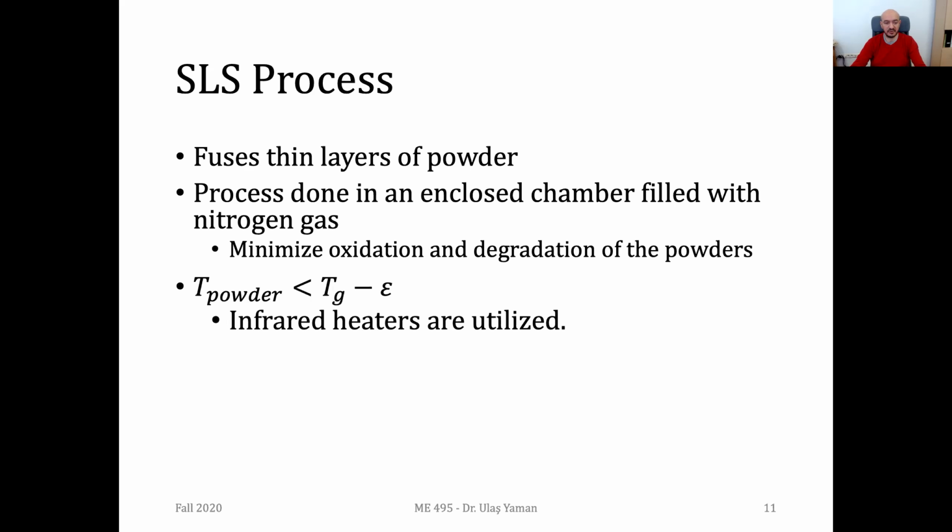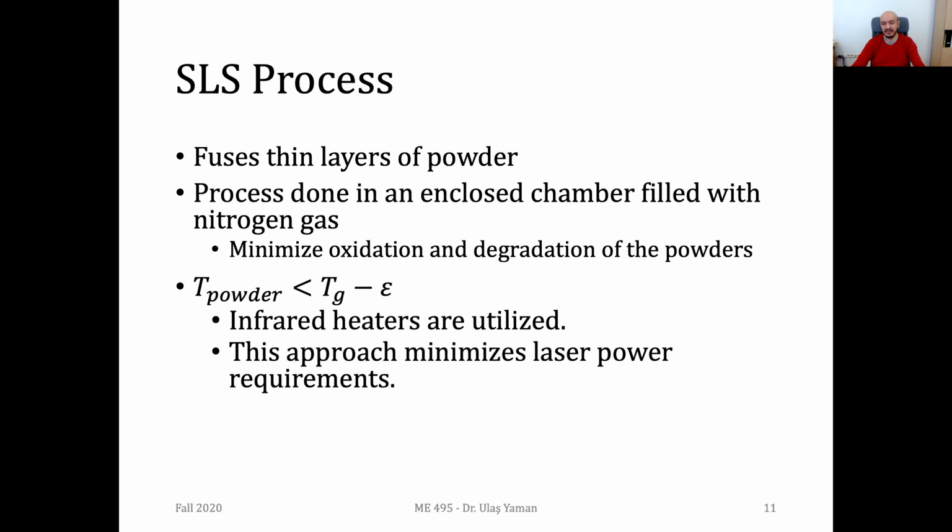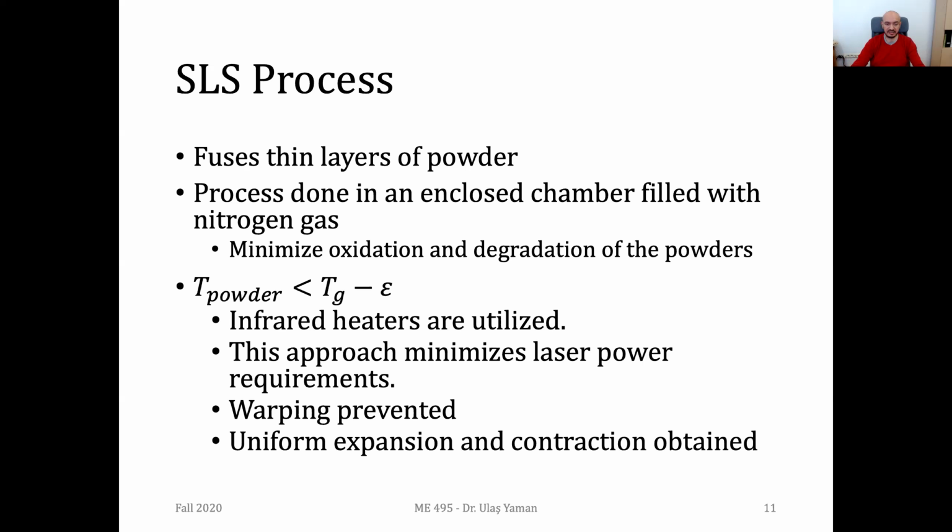And if you remember from the previous slides, we said that some infrared heaters are used in this process so that low power will be required regarding the laser. Another important issue, you have less temperature difference between the environment and the part, and with the help of it, we can prevent warping and maybe some shrinkage values will be decreased. If you have expansion, that will be uniform. You will not have an expansion from a single direction, but we try to have expansion in all directions. Also, it's the same for contraction.